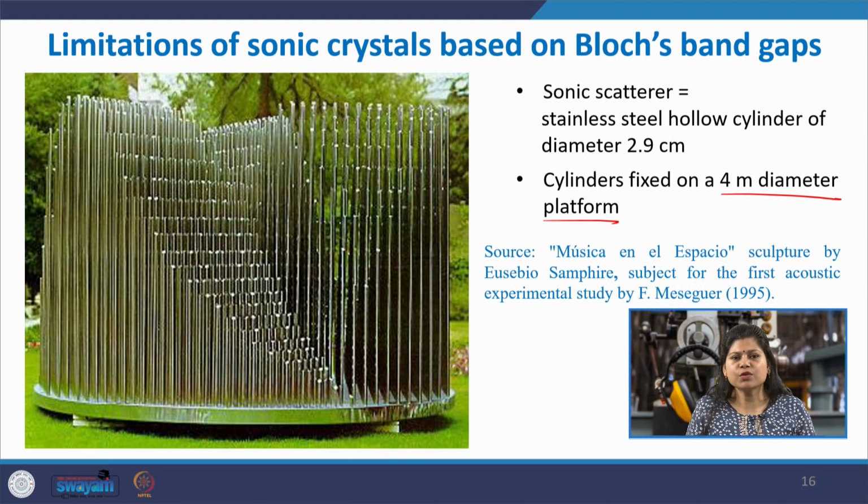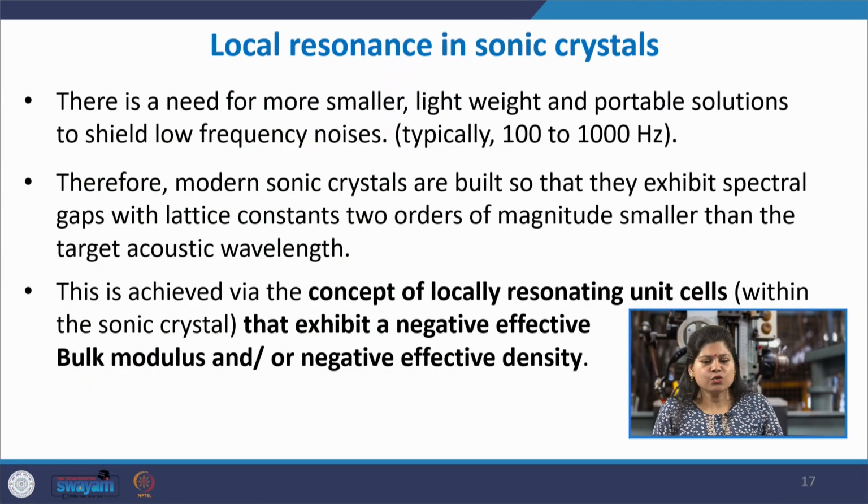But we can't always use these structures, especially when we are dealing with these mechanical systems. In the environmental case, you can always have a big structure outdoors, but what if we are dealing with some machineries and we have some space constraint? So, as I told you, some additional working principle should come into play, and one of that is local resonance. Through the principle of local resonance, you can make sure that the attenuation happens at a lower frequency, and we are not just dependent on the Bloch waves frequency.